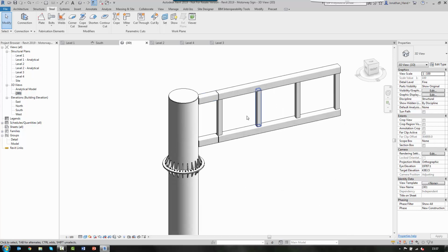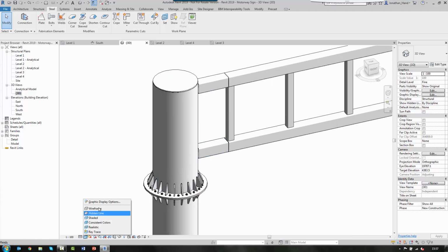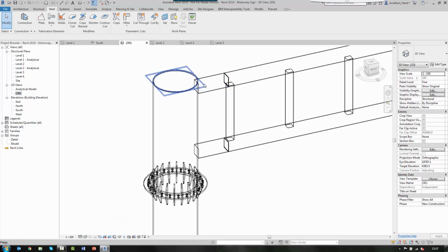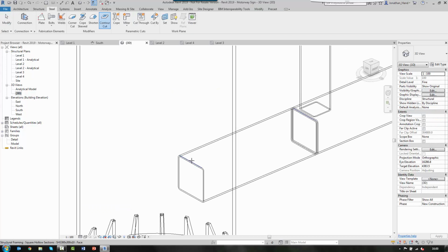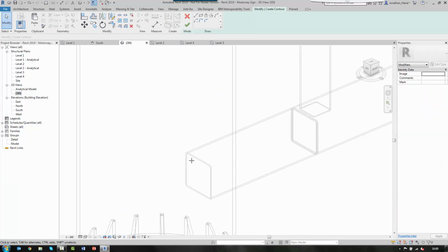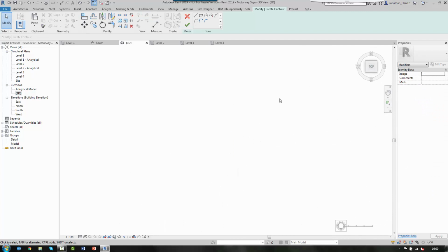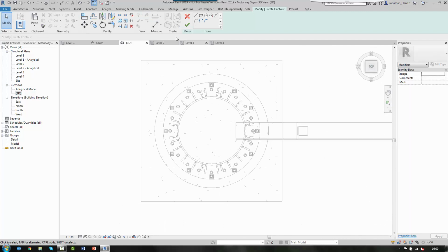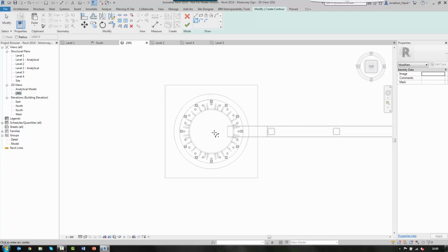So now we get to a little bit of a tricky bit. We just need to select that as the cutting face. Go on the top view just so we can see everything. Then I'm going to use the circle or the center end arc. So I select the center of my component.